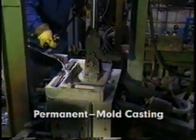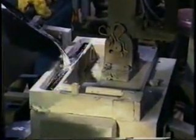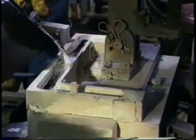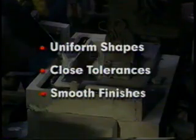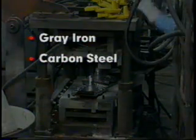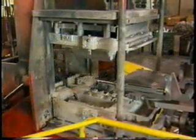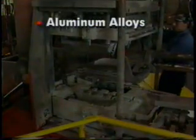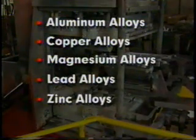Permanent mold casting is a semi-precision process, which because of the chilling effect of the molds, can provide superior mechanical properties. In addition, permanent mold casting can produce uniform shapes, close tolerances, and smooth finishes. Permanent molds are usually made of gray iron, carbon steel, hot-work tool steels, or graphite. Permanent mold casting is suitable for casting many non-ferrous metals, including aluminum, copper, magnesium, lead, and zinc alloys.